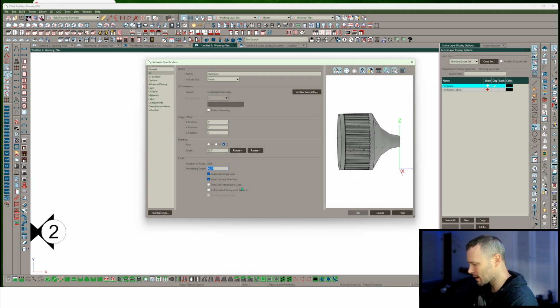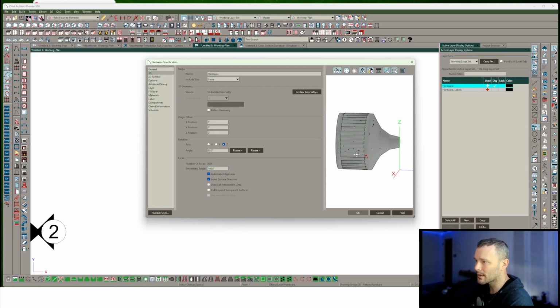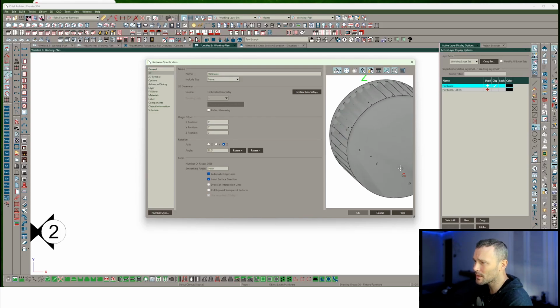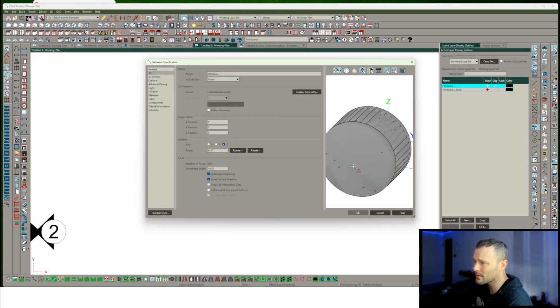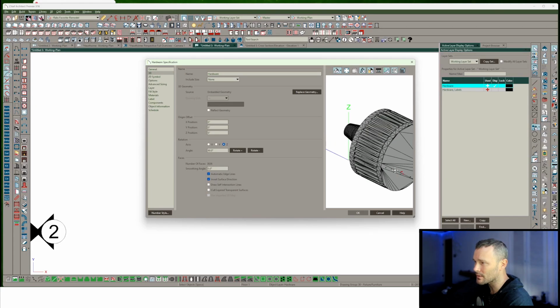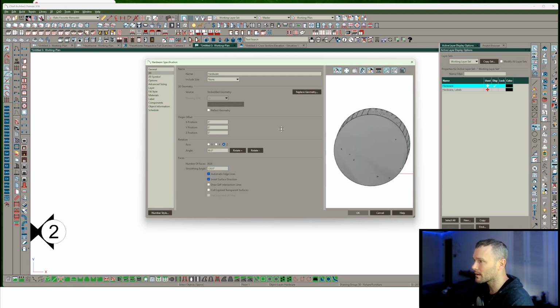And if we kick the smoothing up to like, I don't know, 140 degrees or something like that, we're going to see some sections kind of naturally smooth out in that middle section there. That's pretty cool, right? Now, do keep in mind, this is trying to smooth some vectors on the top here. If we set this back to 0, we're going to see exactly what I'm talking about. It's smoothing these sections right here. So we switch this back to maybe 110, something like that.